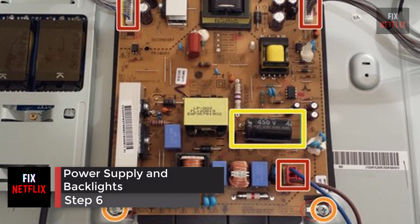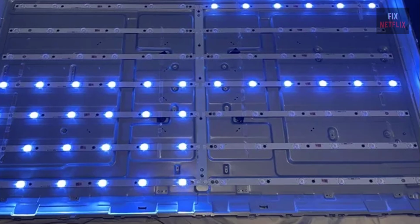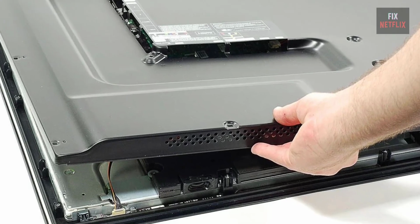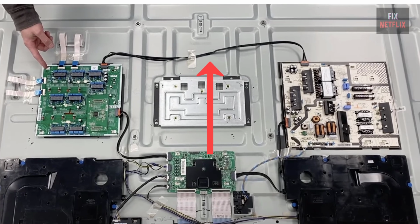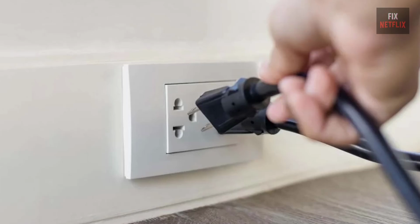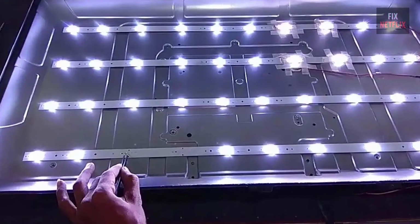Step 6. Power supply and backlights. You can check the power supply and the backlights in one swipe. Make sure the TV is unplugged. Open the back. You may need to remove the base to access all the screws that hold the back on. Disconnect the black cable between the main board and the power supply board. Plug the TV back in. If no backlights come on, you will need to replace the power supply board or the backlights. For now, go to the next step.